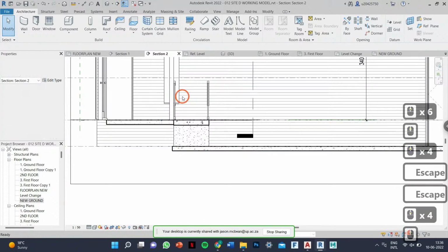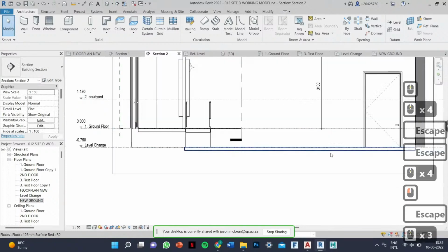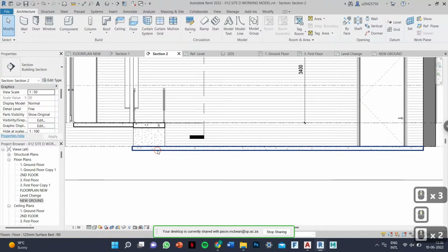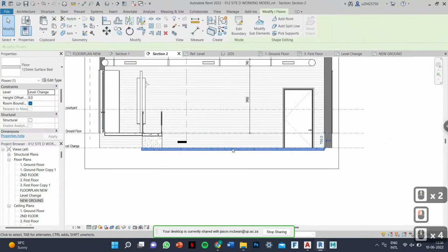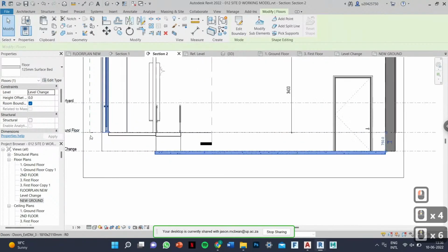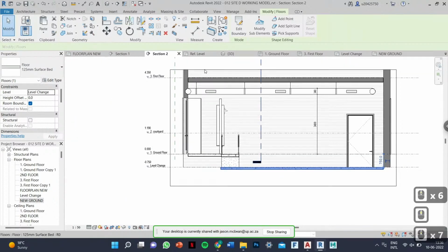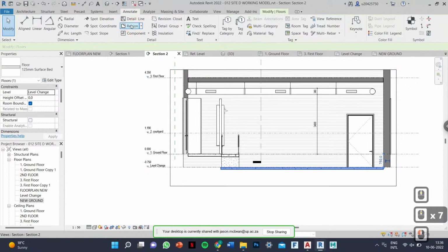Here you can draft in. So now, if I go to 3D view, here I can draft how the concrete step works. Don't worry about trying to model this stuff again, because technically I can hide this in view and then draft like I did and show how the concrete works. Here you can make it all one line. You can literally draft over this with filled regions and masking regions. So you can mask everything and then draft what you want to see.